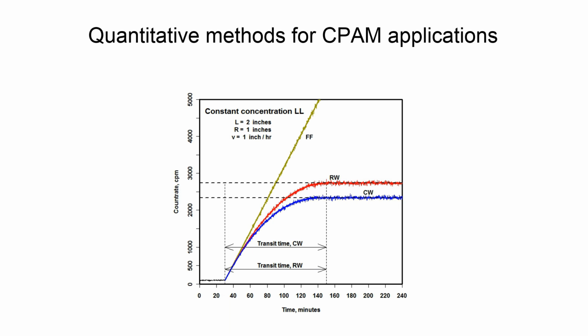This approach was implemented at the SN1 nuclear power plant in the late 1960s for estimating the releases of episodic containment purges, with a predominant and strongly time-varying nuclide of 88Rb. For a long-lived nuclide, the integral term vanishes, and the release depends only on the attained count rate. A similar equation applies for the occupational exposure situation, replacing the stack flow rate with a worker's breathing rate.